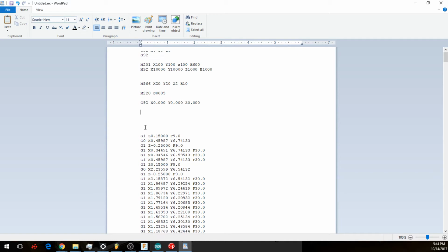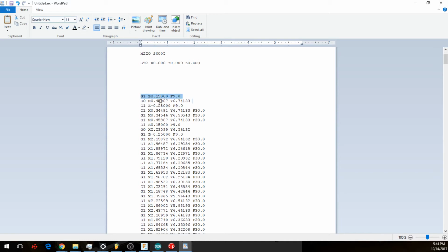But anyways, the first two lines that Easel does: we're going to move to our first position, and then we're going to drop our cutter. Now, Easel has it set up so that it sets the home by hitting a sensor to the build plate and then backing up its command. So we want to actually delete that. We're going to start it up in the air. Give it a little bit of space here.